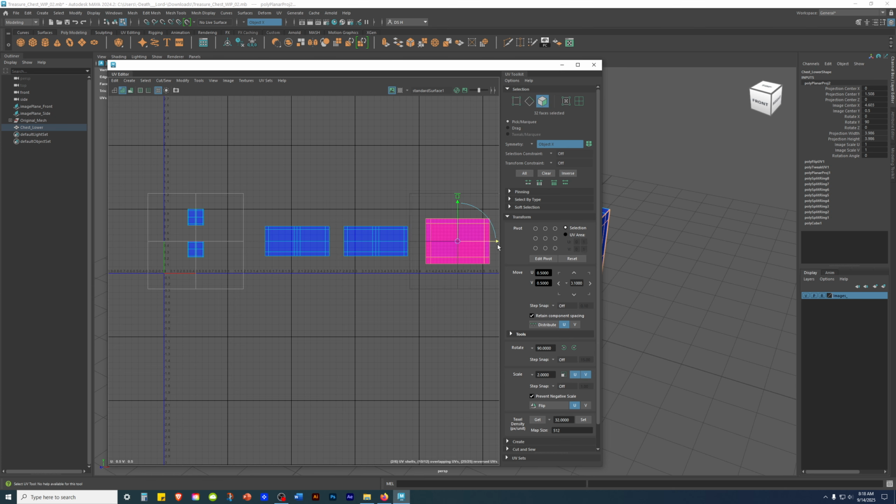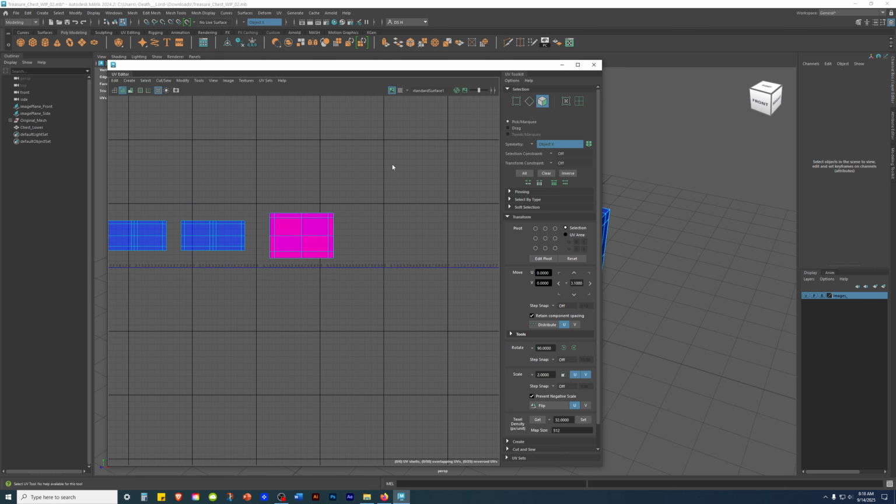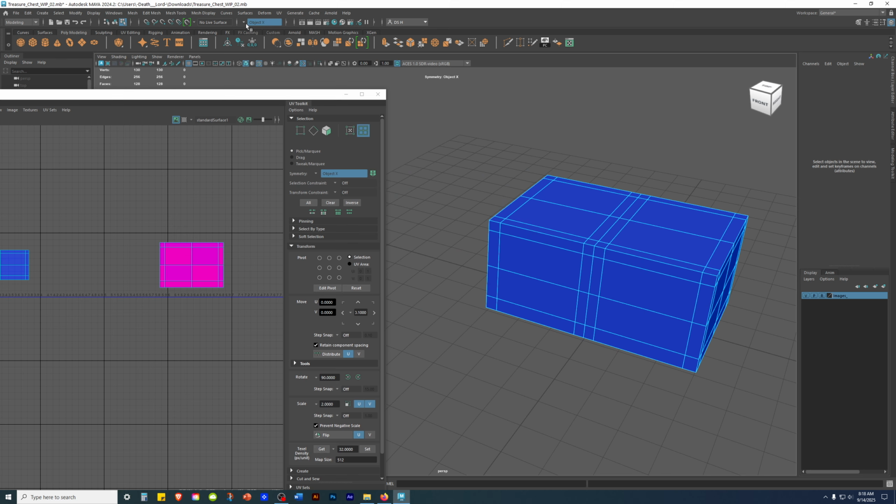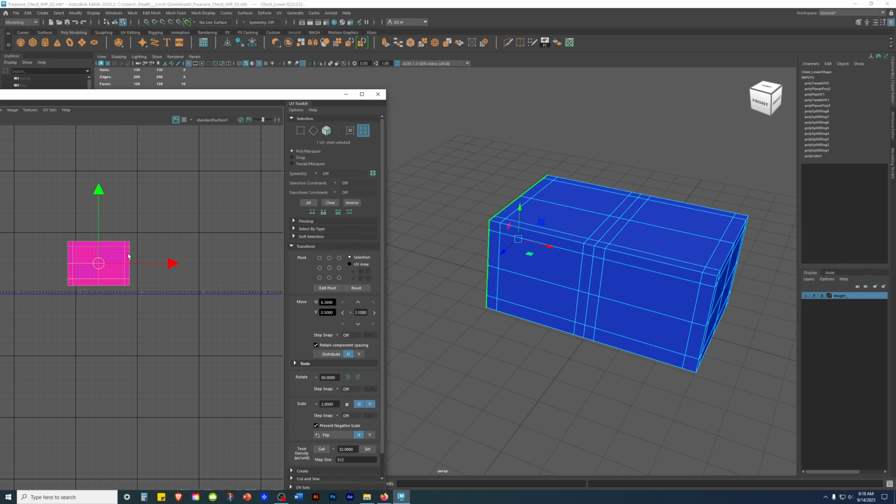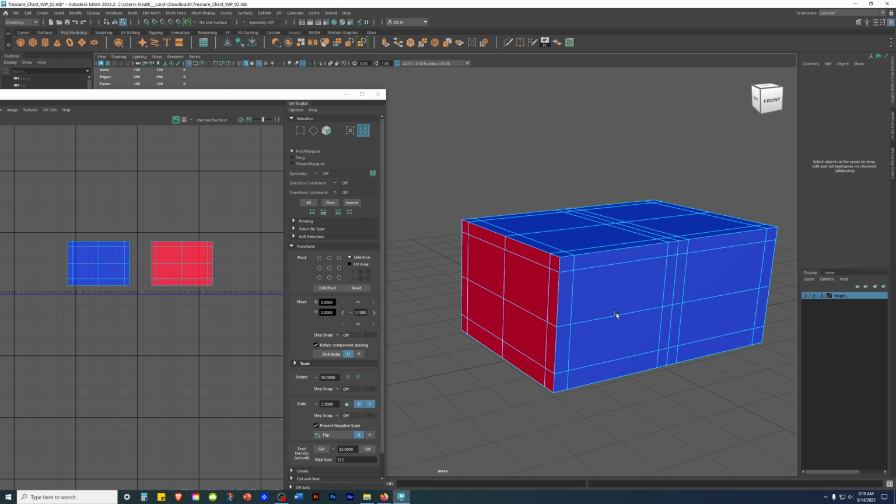That one is here. Chuck it over, grab both sides, right click, hold, UV shell, grab one shell, press W, chuck. God damn it. I have this turned on, I gotta turn that off, because if I have it on, it'll grab both sides, it's goddamn annoying. Right click, UV shell, grab that shell. Flip, meaning turning it around like a top. Boom.